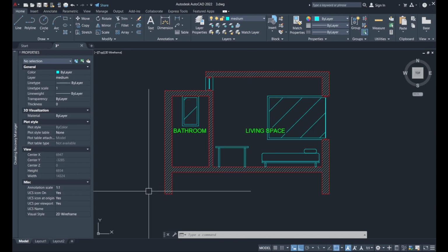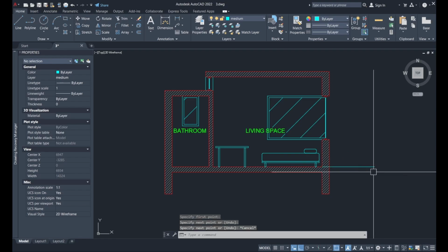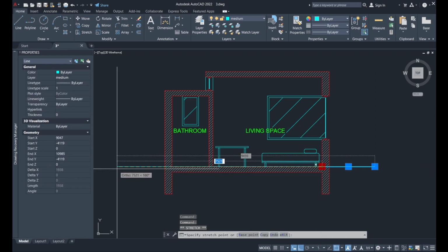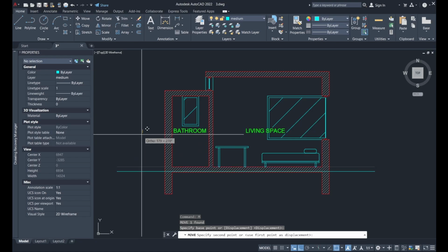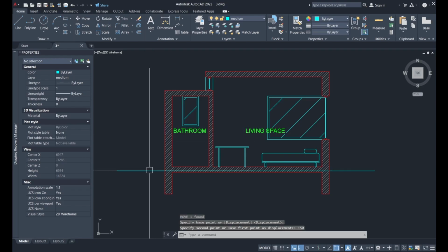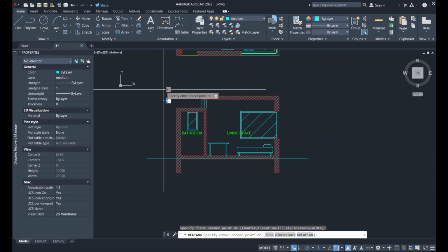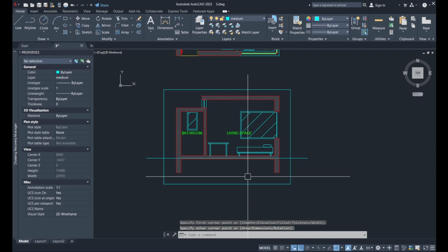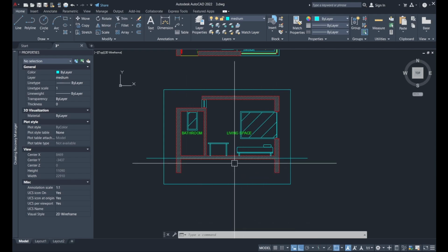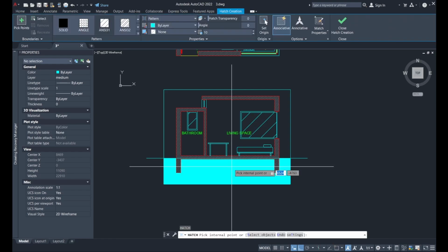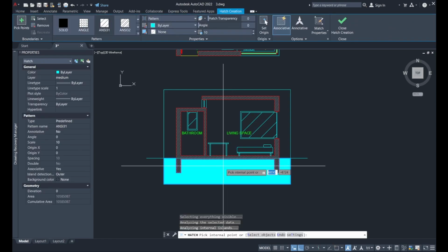Now let's also show the ground level. First let's indicate the line indicating the ground level. Let's move this down by a step, so let's say 150 millimeters. And what I'm going to do is draw a rectangle from this point to here, and I'm going to just hatch the earth. So I can use that rectangle to create a region here.